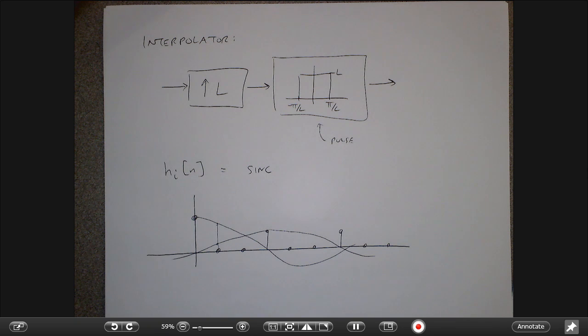And the question is, is there a more efficient way of doing it than to basically upsample by a factor of 103 and downsample by a factor of 100? Because in doing that, I'm generating lots and lots of extra samples that I'm throwing away, right? And so the topic of the next lecture is going to be what I would call multi-rate signal processing. The theme is how do we do signal processing operations in efficient ways where we're not doing a big filter and then throwing pieces away. We want to make sure that our computation is as efficient as possible. You can do that by decomposing some high-rate signal into a bunch of lower-rate signals. And that's what we're going to talk about next time.